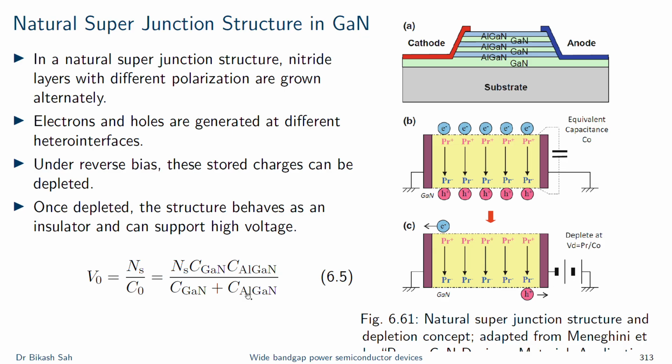The important idea is that polarization engineering can mimic the charge balance principle of superjunctions without conventional doped PN columns.